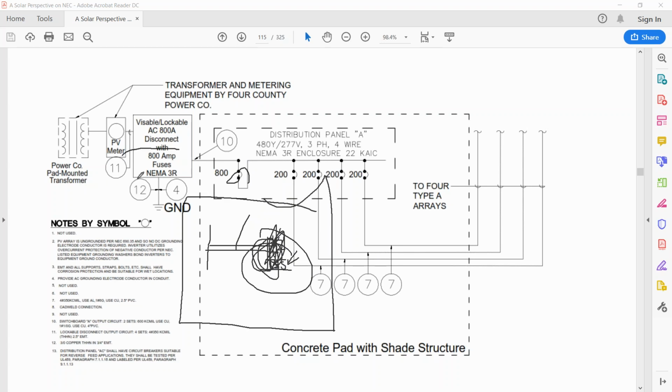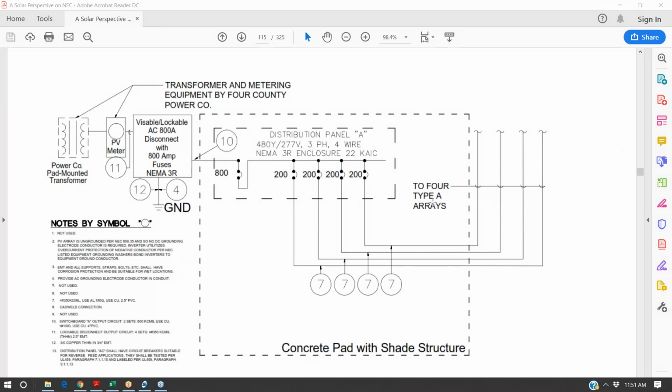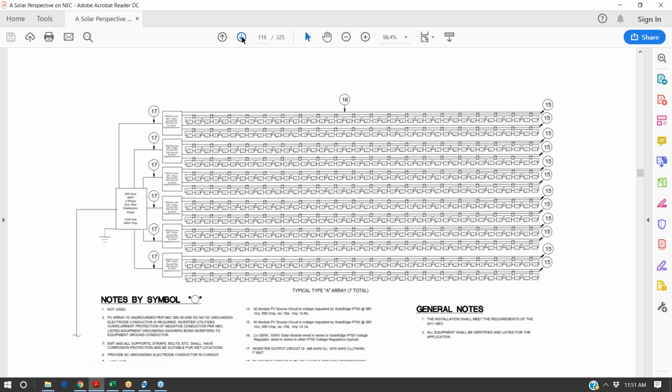Whereas if it had been a fuse instead of a breaker, the problem would not have occurred. And then you're kind of idiot-proofing the system, because it would force the installer to come back out there and replace the fuse and see what's going on before the problem got worse. But just beware of breakers tripping and you resetting them. They shouldn't trip for no reason.